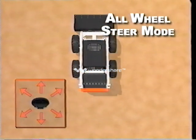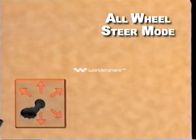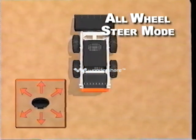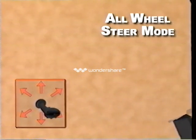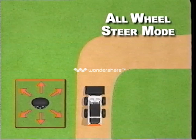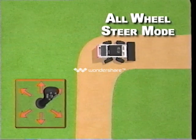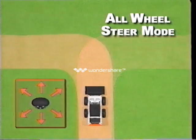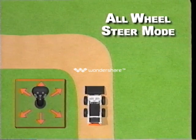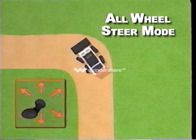To turn left in reverse, pull the joystick back and to the left. To turn right in reverse, pull the joystick back and to the right. The joystick moves in a C pattern when changing from a forward right turn to a backward right turn. Reverse the joystick pattern when changing from a forward left turn to a backward left turn.